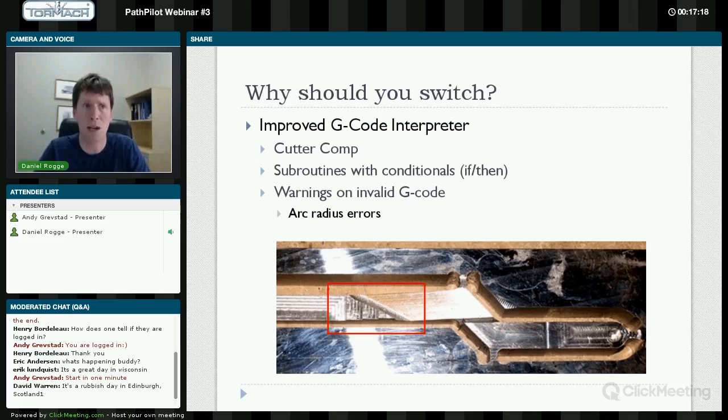If you program G83 with a P word and your control software doesn't warn you that that's invalid, who cares? Maybe you thought that it would dwell at the bottom of the cycle and it didn't. You know, that's not that big of a deal. But I, for one, would like to be told, if I have a p-value on the line, I'd like to know that that wasn't going to be respected. With Mach 3, it would happily just chug through the code and wouldn't tell you anything, and just would throw out the p-value. And that's of low consequence, right? I mean, I think we can all agree, it's not ideal, but if that's the way it works, so be it. But that's not the only bad code that our old software would accept.